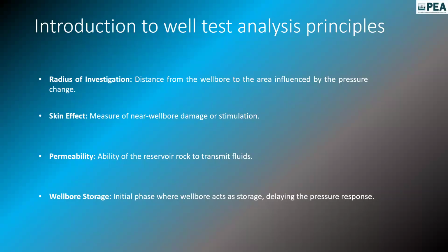Once you open the perforations, because of the pressure difference, like a shock created near the wellbore, some part of these drilling fluid materials falls back into the oil, and it starts moving into the wellbore inside the drill pipe. This kind of material debris, once it mixes with oil, gives an impression as if oil is coming into the wellbore. How can we identify this?